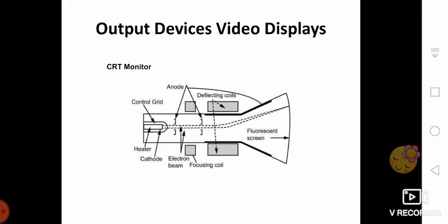An interlaced display, particularly at a relatively low refresh rate, can appear to some observers to flicker, and may cause eye strain and nausea. The intensity or strength of the electron beam is controlled by setting the voltage levels. The number of electrons that hit the screen determines the light emitted by the screen. When the voltage is varied in the electron gun, the brightness of the display also varies.